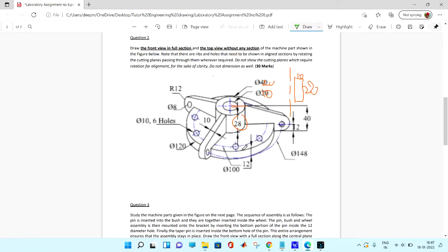Now you can see the base has, from the center, a radius of 120 mm, 120 mm from here, and the depth is 12 mm. So how much is the rectangle here? It will be 50 by 12, because this is 60 from here to here, but there is a gap of 10 mm, so it will be like this. Now we will revolve it. When we revolve it, this will be ready.